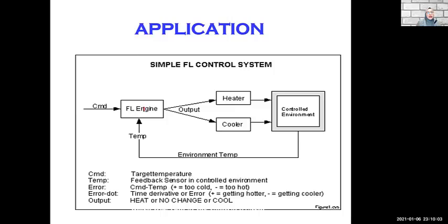So the fuzzy logic engine will read the input from the command CMD, and then it will generate or increase the heater or reduce the cooler, or either one, depending on the output from the fuzzy logic engine. So this will control the environment temperature. So error is the difference between CMD and the feedback temperature from the sensor.